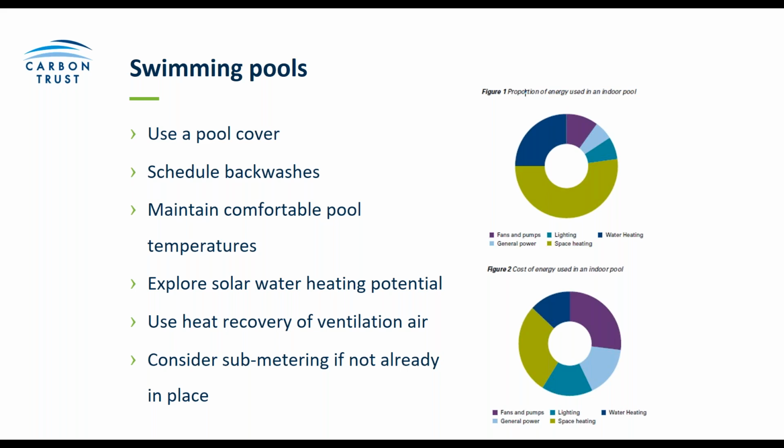So making sure that a pool cover is used overnight, make sure that backwashes are scheduled appropriately and not more than necessary. Make sure that pool temperatures are comfortable, that you're not overheating the pool water or the air around it.